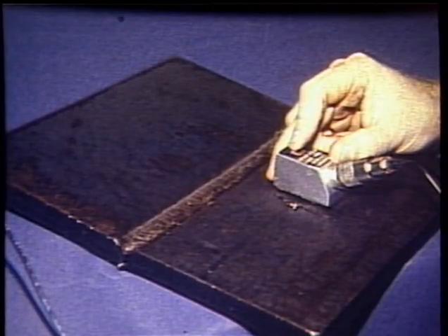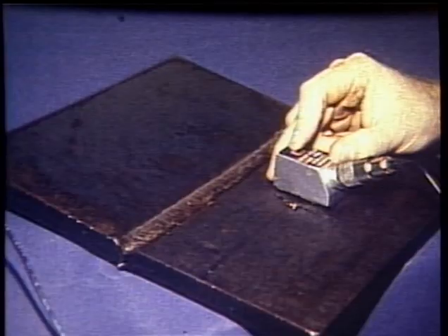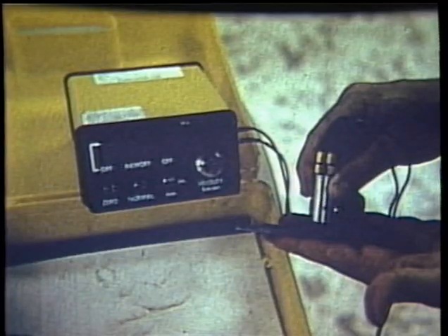Unlike other non-destructive tests, one of the most outstanding features of ultrasonic testing is its capability of accurately determining the location and depth of flaws. It can be used on practically all non-porous metals with a fair amount of speed. The equipment needed is normally small and can often be operated by battery, which makes it convenient for field applications.